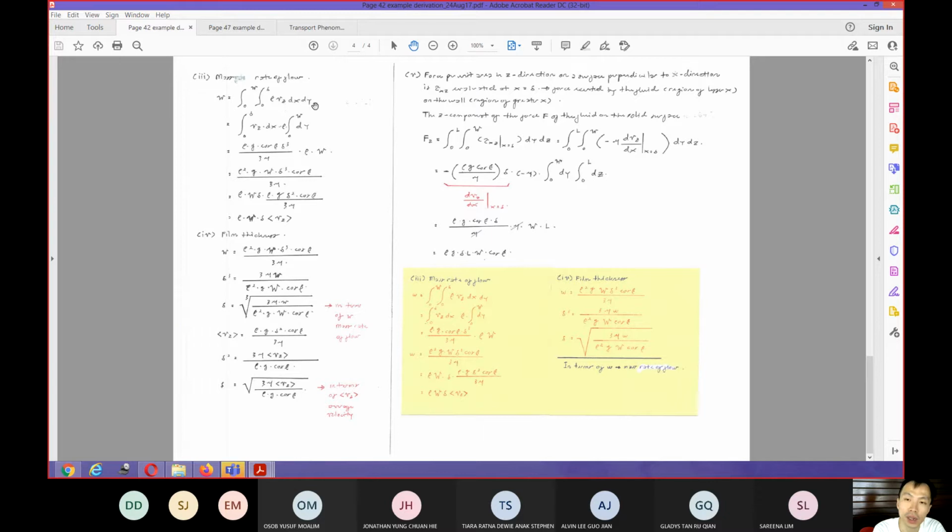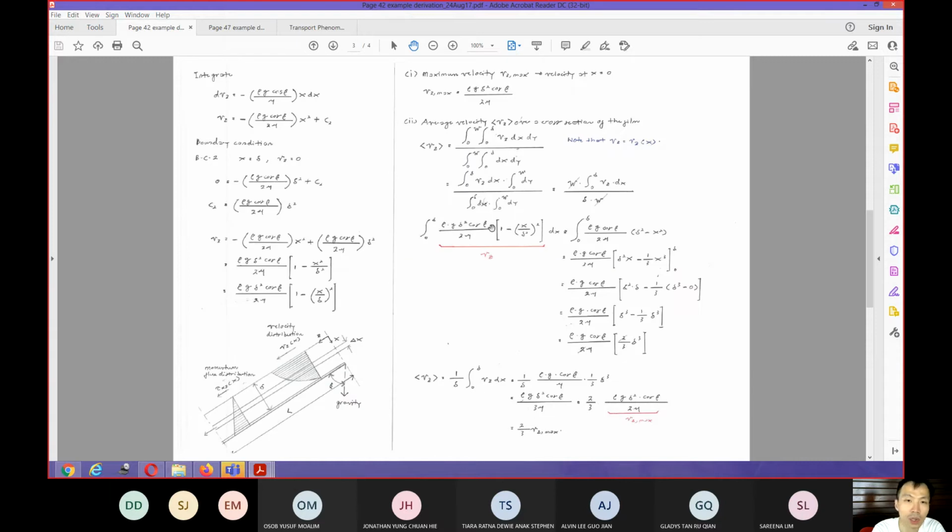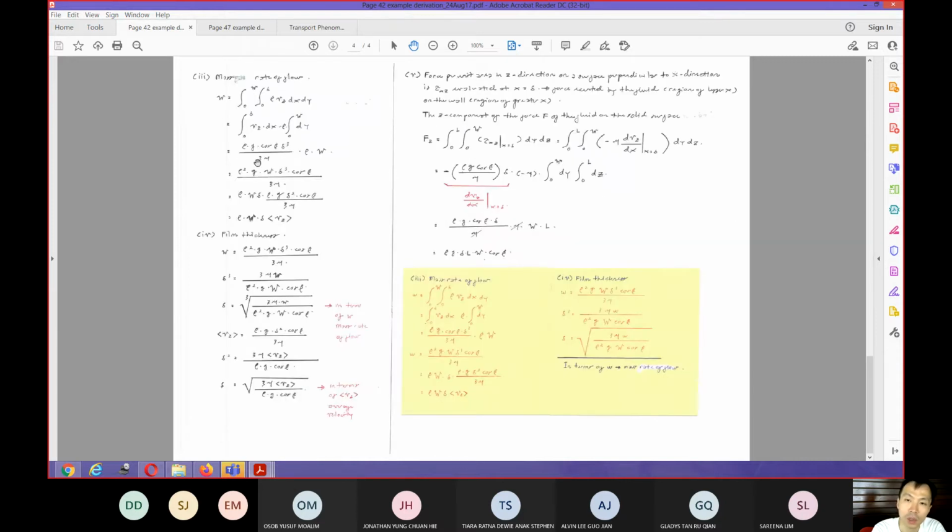You can check the units again. If you multiply the units of this one, for example, this density is normally given in terms of kilogram per meter cubed, then you multiply by meter per second, and then by meter, and then by another meter, and then your unit will be kilogram per second. So you need to always check the consistency of your units. Okay, if you do the same thing that you did for that one, what you will get is basically this one multiplied by another rho. So that will be simply these terms in here.